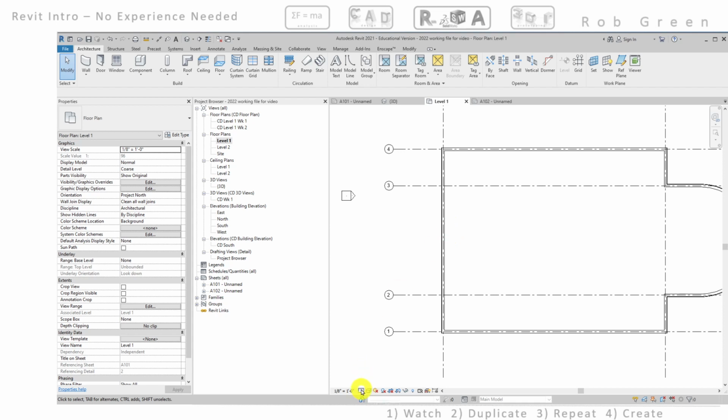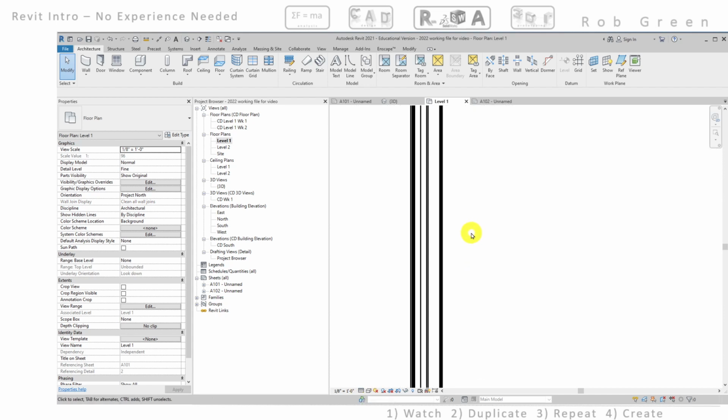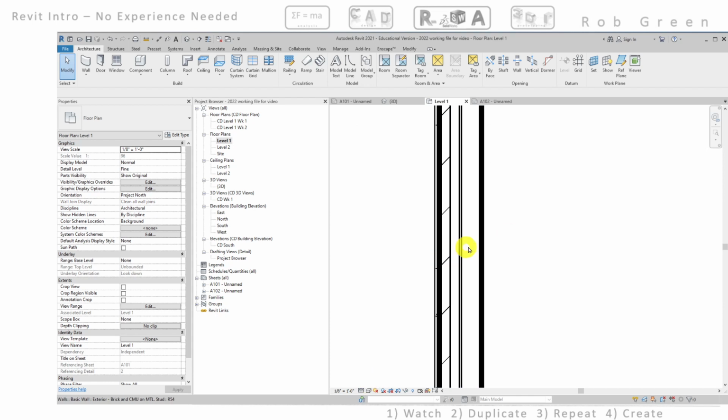to. And so we've just touched on these view resolutions in person to person in class. For just about any project that you're working on, fine view resolution is probably the best place to be looking at a model. Many exceptions to that, but certainly as we're beginning, we always want to use a fine resolution. Notice that the look of the wall changed, and if I zoom in, I can see multiple lines now. And notice they all have different line weights.